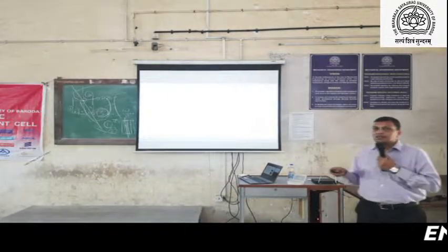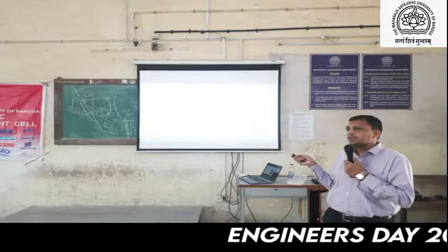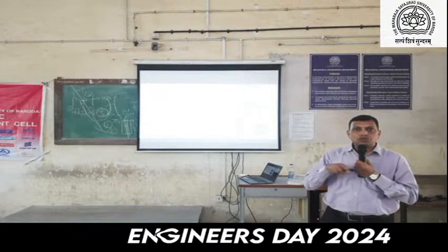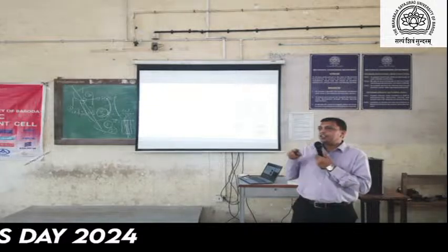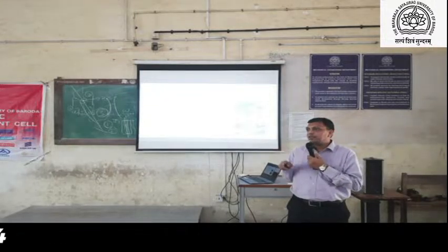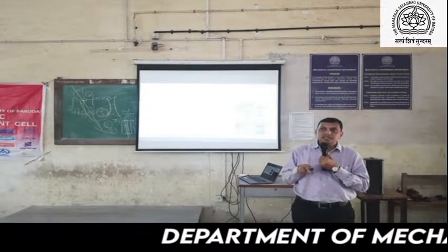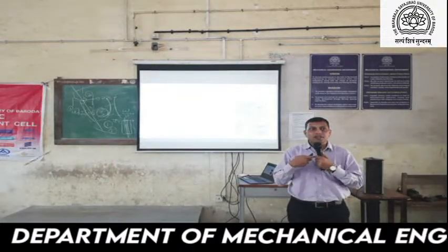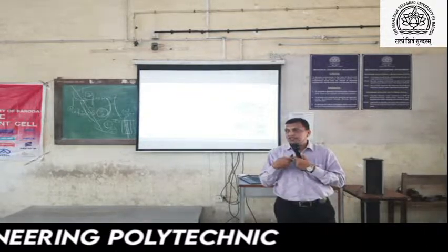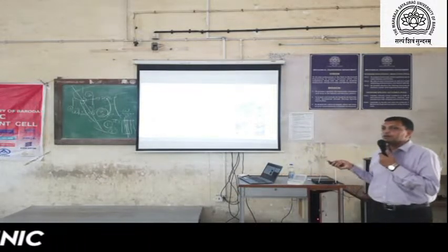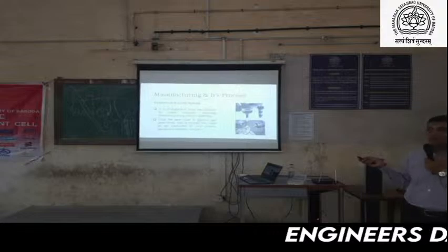Then inspection of the profile. Basically it is used only for very special cases, and the profile is measured on the tooth and can generate one graph. That graph is related to the already defined one, and it should be matched with that. Another thing is that if we are making matching components for the first time, we have to check the profile of both teeth, and they should be matched. This will help us with good contact as well as backlash maintenance.